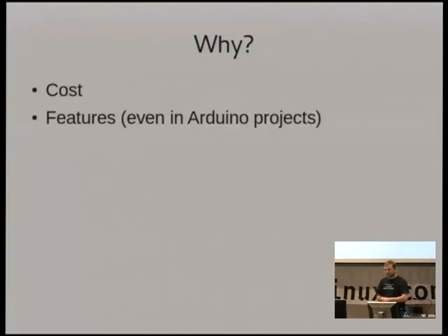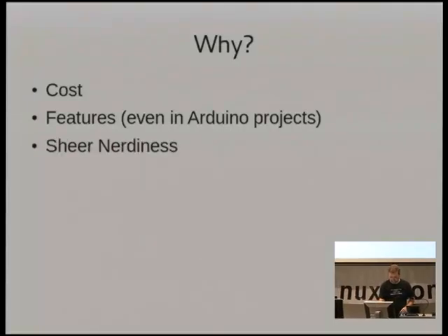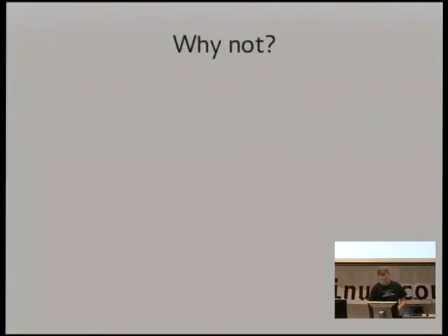The other thing is that there are a number of limitations of using Arduino, like only being able to have interrupts on a couple of pins, or only being able to do PWM on some pins. And sometimes that's really irritating. And it turns out you're not actually limited by the hardware to doing that. It just happens to be easier to do it the way that Arduino has done it in the hardware. There might be other reasons too.